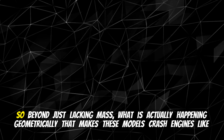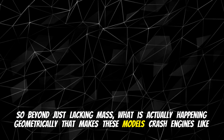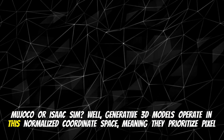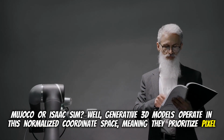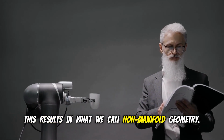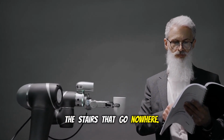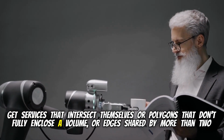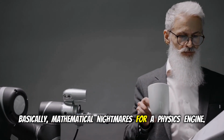It shatters, yeah. So beyond just lacking mass, what is actually happening geometrically that makes these models crash engines like MuJoCo or Isaac Sim? Well, generative 3D models operate in this normalized coordinate space, meaning they prioritize pixel-level appearance over geometric truth. Okay. This results in what we call non-manifold geometry. Think of it like those Escher-style impossible shapes. Oh, right, the stairs that go nowhere? Exactly. You get surfaces that intersect themselves, or polygons that don't fully enclose a volume, or edges shared by more than two faces. Basically mathematical nightmares for a physics engine.